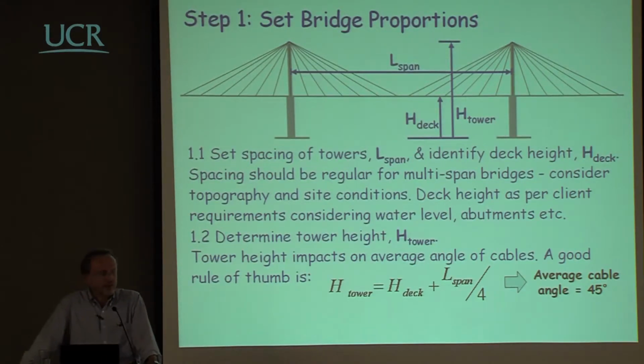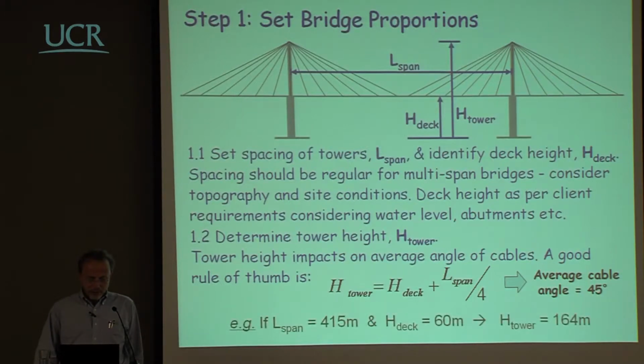So based on this, you try to have a first guess on the geometry, which means to dimension the total height of the tower essentially as a proportion to the span that you need to have. And maybe what you will do is to have something where the height of the pier is in the range of, say, 25% of the span or something like that.